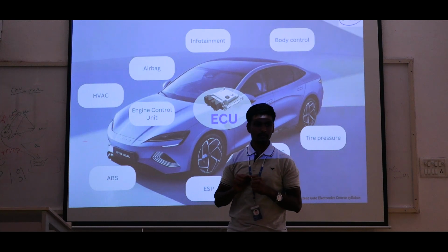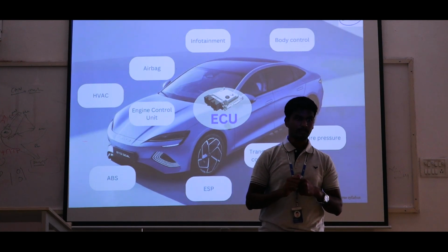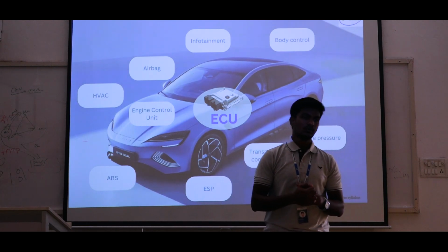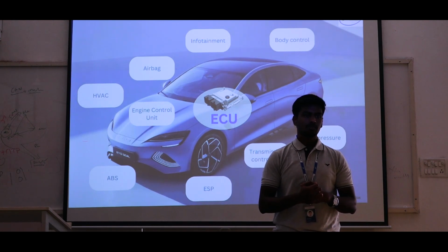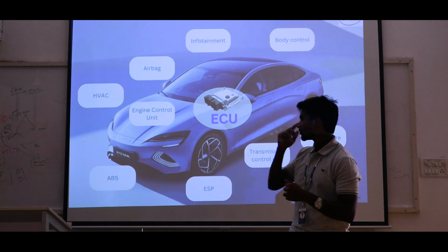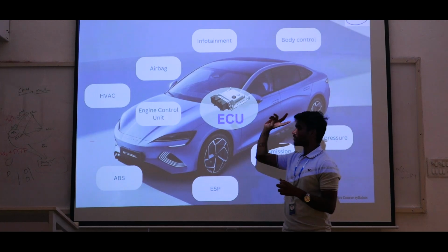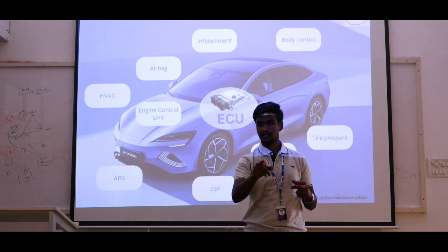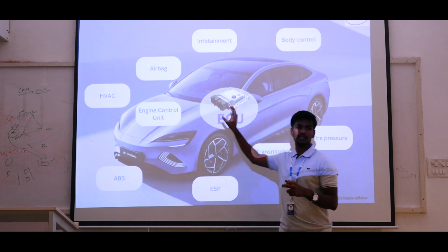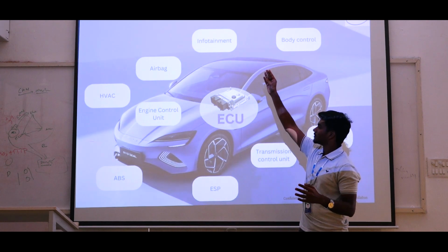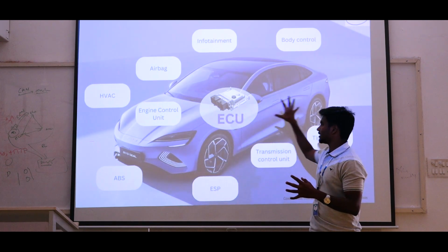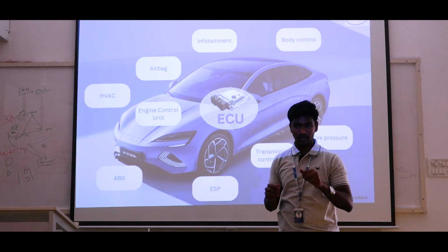Whether these sensor inputs are given to these ECUs, generally we give the sensor inputs to some microcontroller. Now, for the ultrasonic sensor example, will that sensor value be given as an input to this ECU? For example, the ultrasonic sensor will be detected by the RPAS, the reverse parking assistance system, which is one ECU. Another ECU we can take is infotainment, and the ABS, the anti-lock braking system. These three ECUs are communicating over two wires.